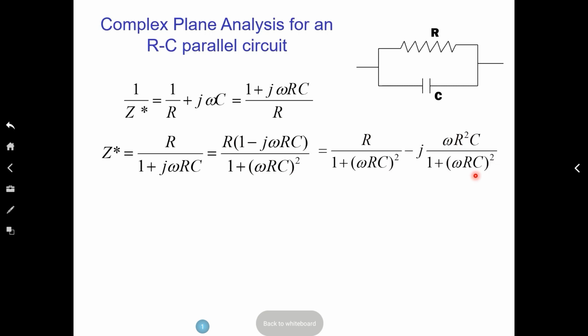This is exactly the calculation you repeat, ultimately giving you, at each of the frequencies, the so-called Z prime, which is the real part, and Z double prime, which is the imaginary part. And you can see those are going to change as you change frequency. So different frequencies give different Z prime and Z double prime. So overall, the impedance of your sample will be given by this.